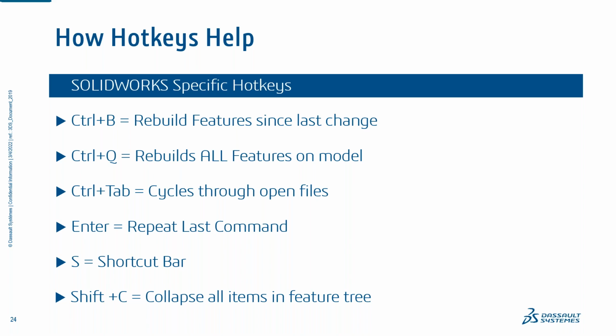Enter is the repeat command. So say you're doing lots of mates, mating a full assembly with lots of hardware being put in there, or you want to do a lot of patterning. Every time you hit that Enter key, it'll repeat that last command over and over again. It keeps you from having to re-click that button and set your settings back up. We already spoke about the shortcut bar, the S key.